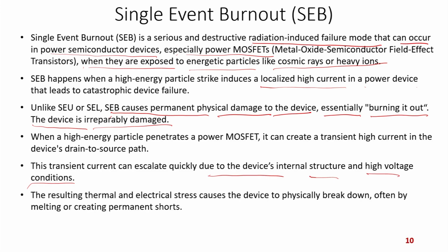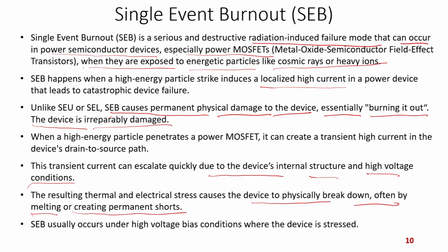And the resulting thermal and electrical stress cause the device to physically break down, often by melting or creating permanent shorts. So, SEB usually occurs under high voltage bias conditions where the device is stressed. So, this is also, if I say, the SEB is also a hard error.